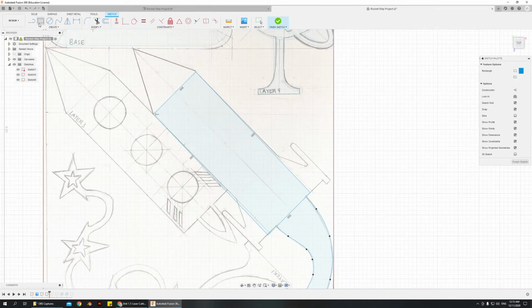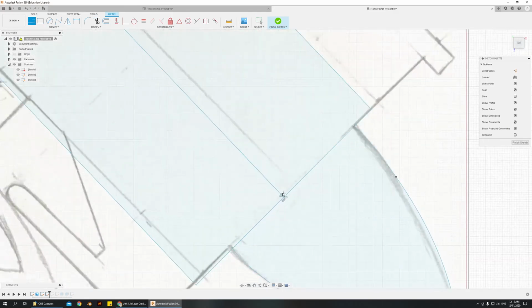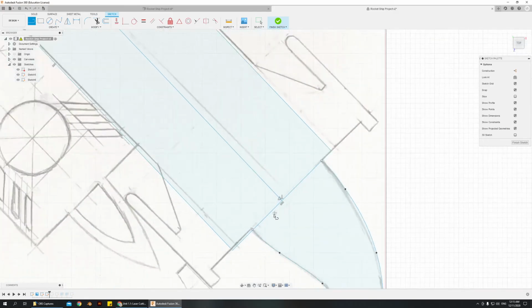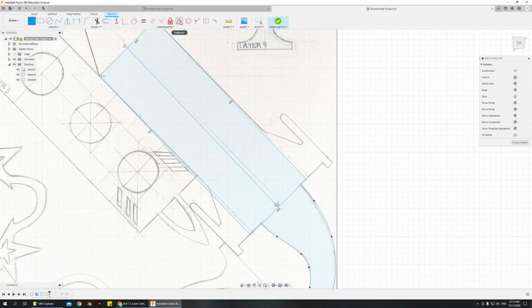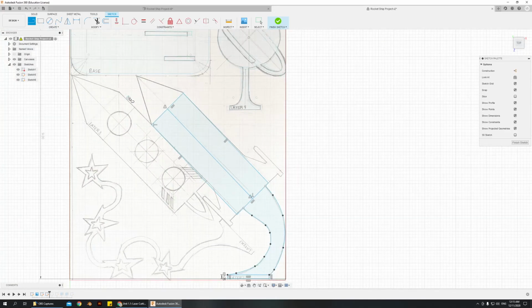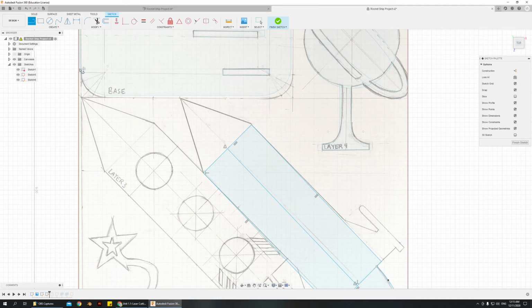What I also did is I created a reference line. So you create a line that's in the midpoint of this shape. That triangle means midpoint. That's a constraint that means it's locked into the center. That's what I did to create this correctly. Now I can go from here, and then it creates that line that allows me to know that it's on the midpoint, and then from here to there. And that allowed me to constrain it correctly.